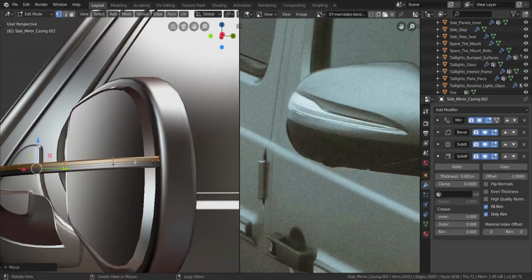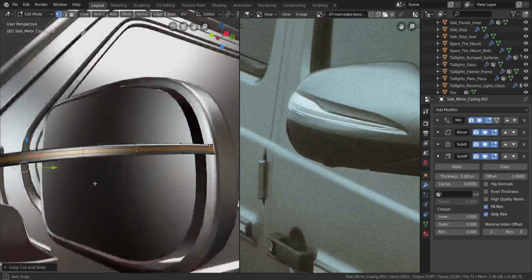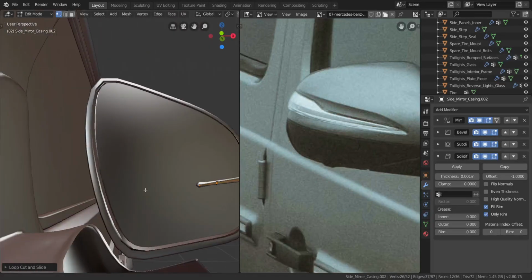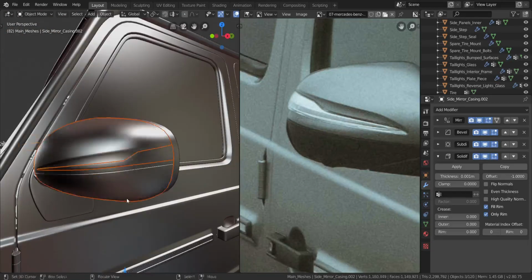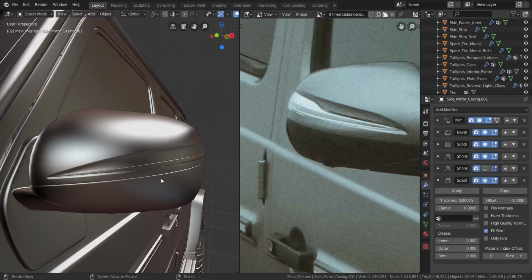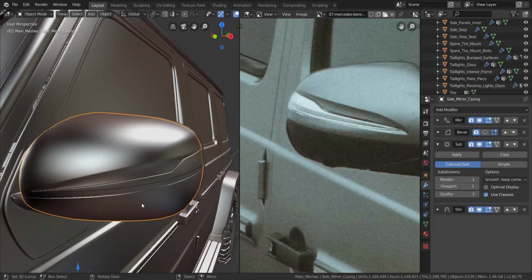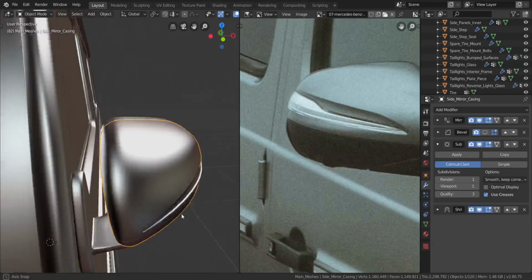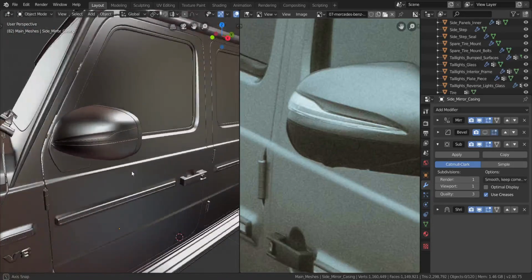Alright, there we go. So I want to dissolve this edge, dissolve that edge. And let's add in 2 again, so they're in the middle. Like that. And there we go. So let's press Alt and H to bring everything back. Let me hide this. And nice. So that pretty much does it. Let me see. Yeah. That about does it. So you can rename this whatever you want.